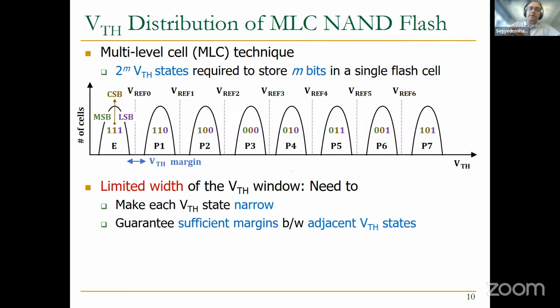Also, you saw in the previous meetings that the endurance of a TLC NAND flash chip is lower compared to SLC, and that's one of the reasons, because the accuracy needed to read perfectly is higher. You need a more accurate read and you have lower margins in TLC. As a result, you cannot use your flash cells accurately for a long time.